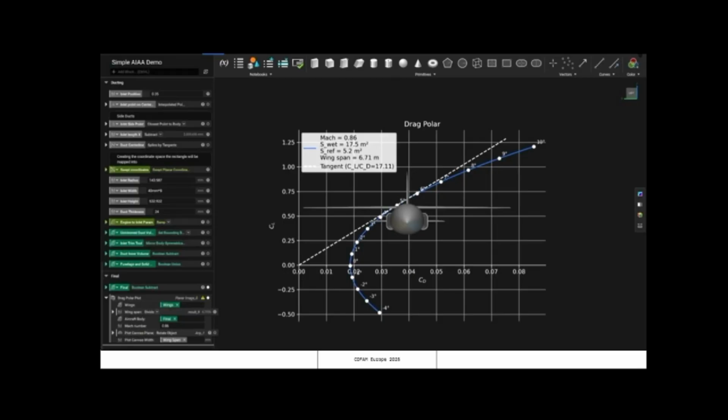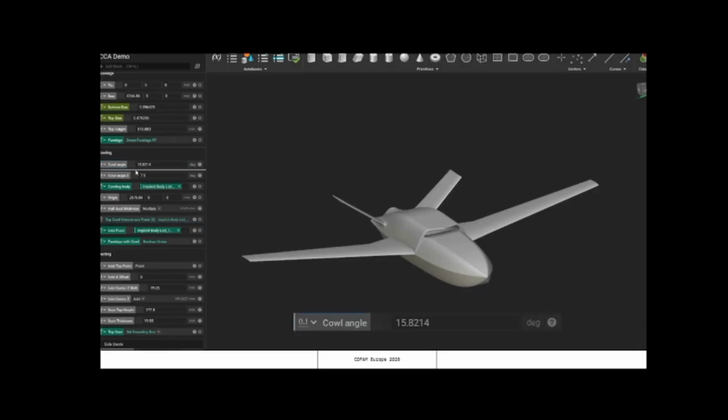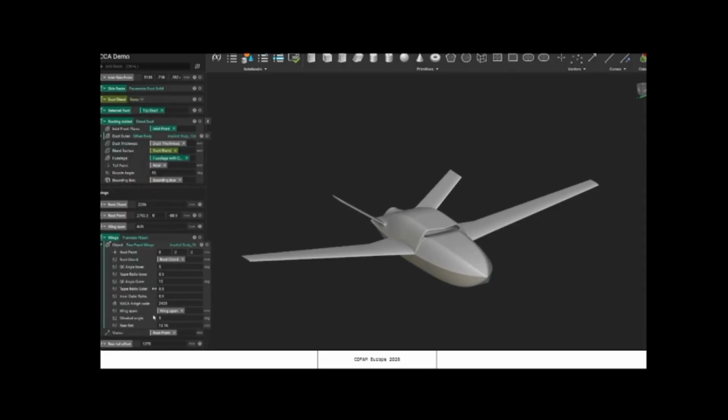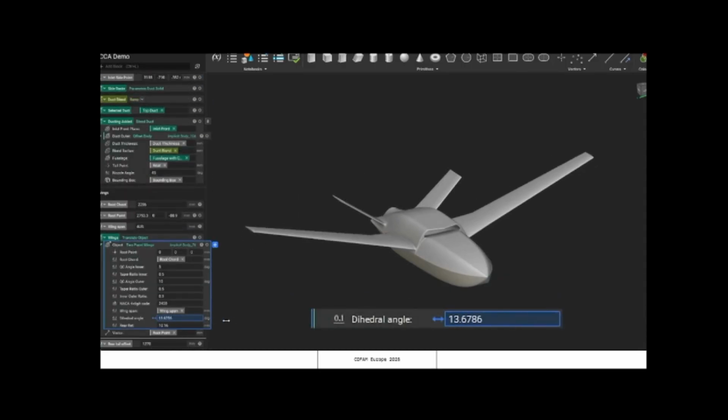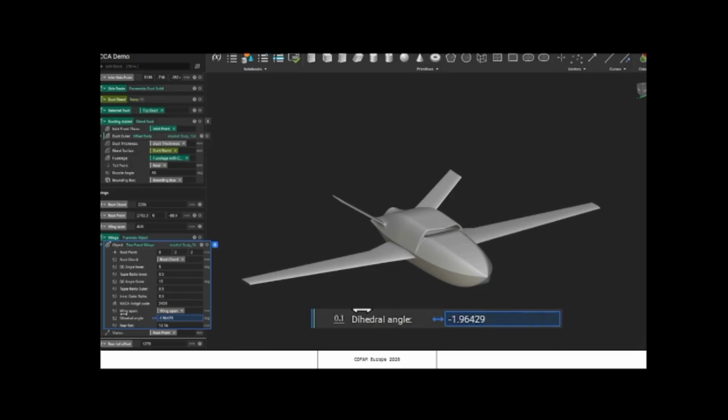You can connect that model to different analysis methods. Maybe it's more simplified panel methods for CFD. One of our team members connected Xfoil into nTop, or you can connect to VORLAX solvers and stuff like that. But I think what was most impressive was those same blocks were then just reconfigured into the CCA vehicle in less than an hour, put together, and it's fully parametric.